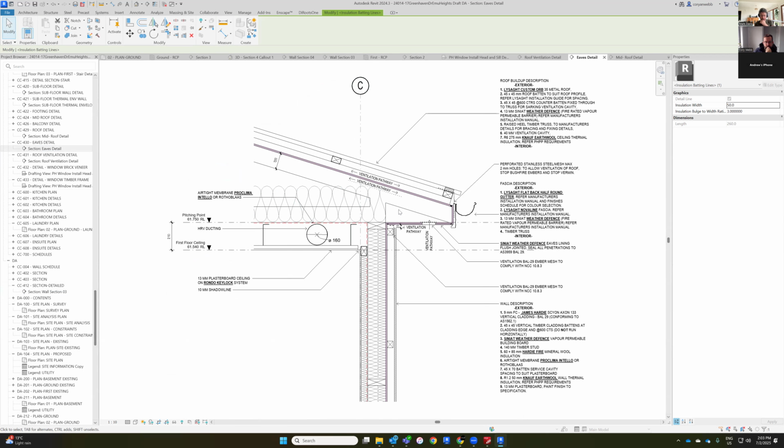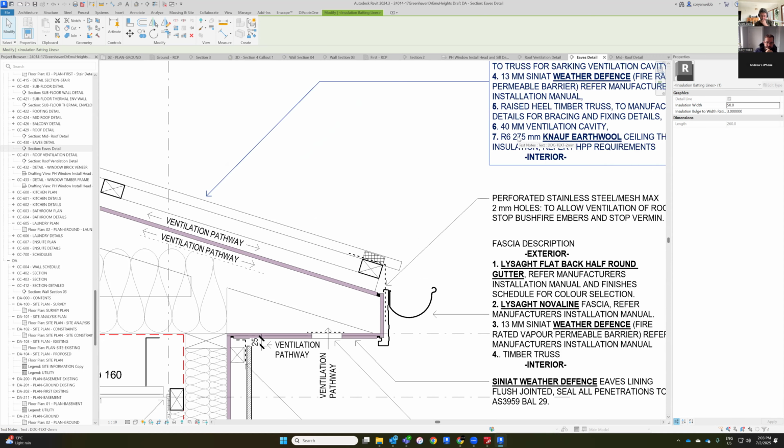So the R4 ceiling insulation is deeper than R4 wall. I think it's about 195 or something. Okay. Yeah, I'll have a check. At the moment, I've got it as 275 R6, so I'll double check. 270, 195, 295. You might be a little bit short. Okay.